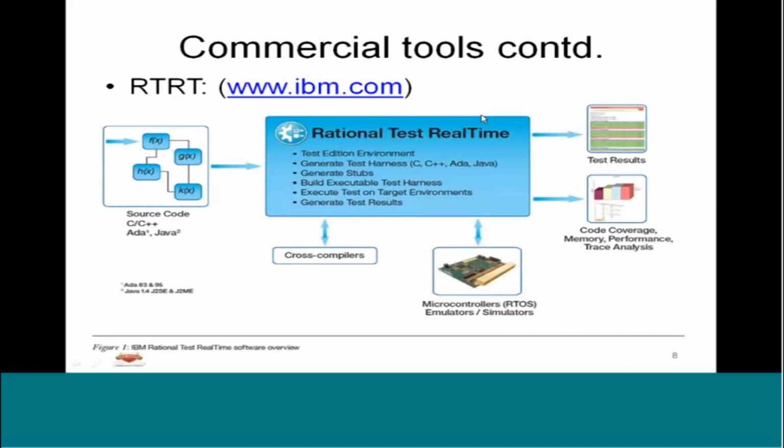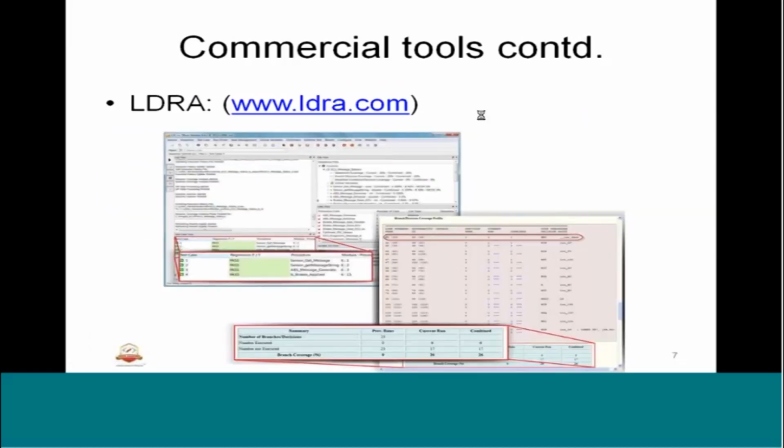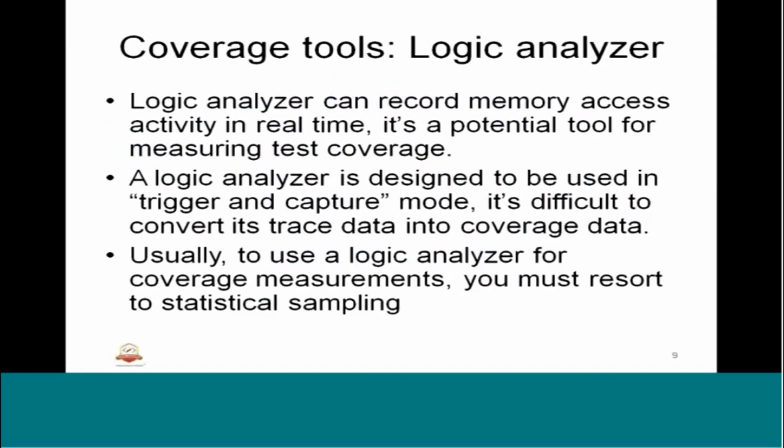Okay, so that is about the commercial tools used for white box. So let us try to study what a logic analyzer is. Basically, a logic analyzer can record memory access activity in real time. It is a potential tool for measuring test coverage.